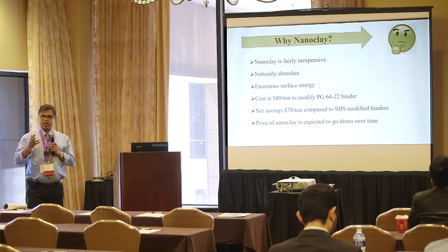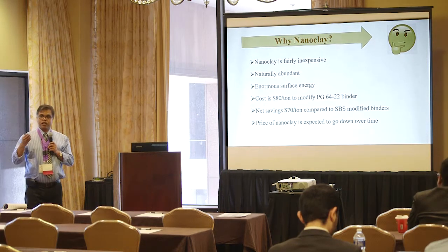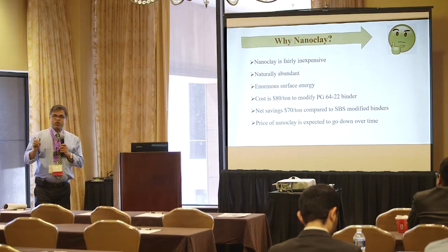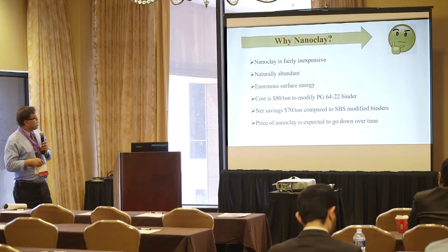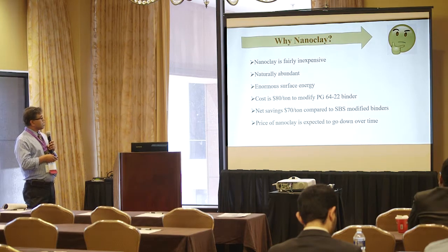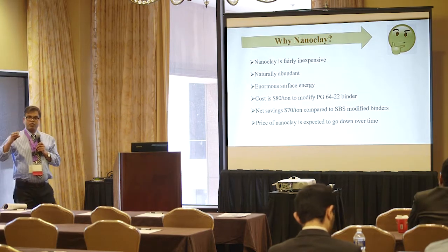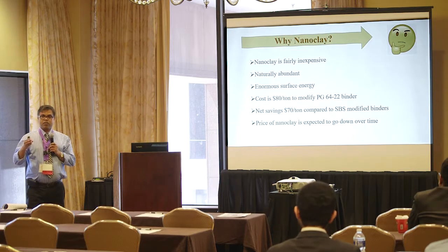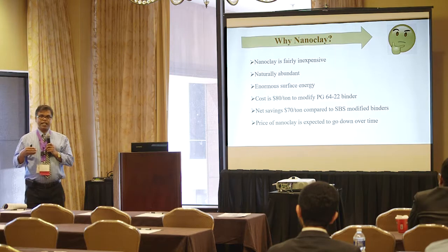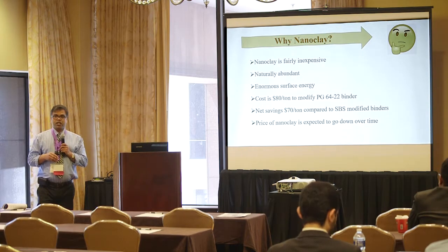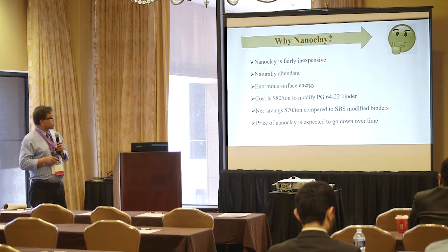It is usually better if you can modify it with a potassium ion. Otherwise, in general, montmorillonite has the H+ ion there. But it has enormous surface energy. Once you have high surface energy, if you can treat it well and blend it properly, then it is expected to give you better performance properties.